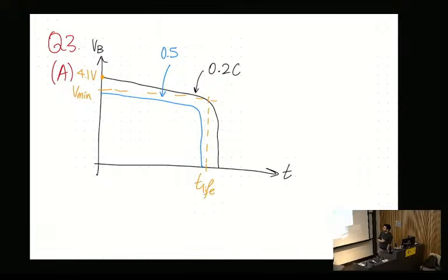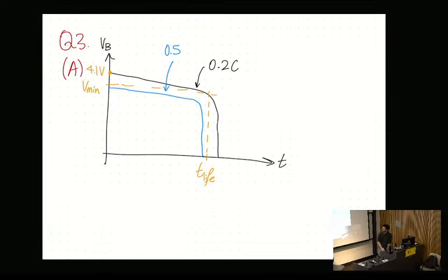So we have some battery and some charging rates. Now, the rate at which you charge and discharge a battery is really important. And as a fun fact, does anyone know why lithium-ion batteries always explode on the news? What is it about the battery that people do that's wrong? Yes, they overcharge the battery. So it's not specifically the battery itself, but they're charging it at a capacity that it's not rated for.